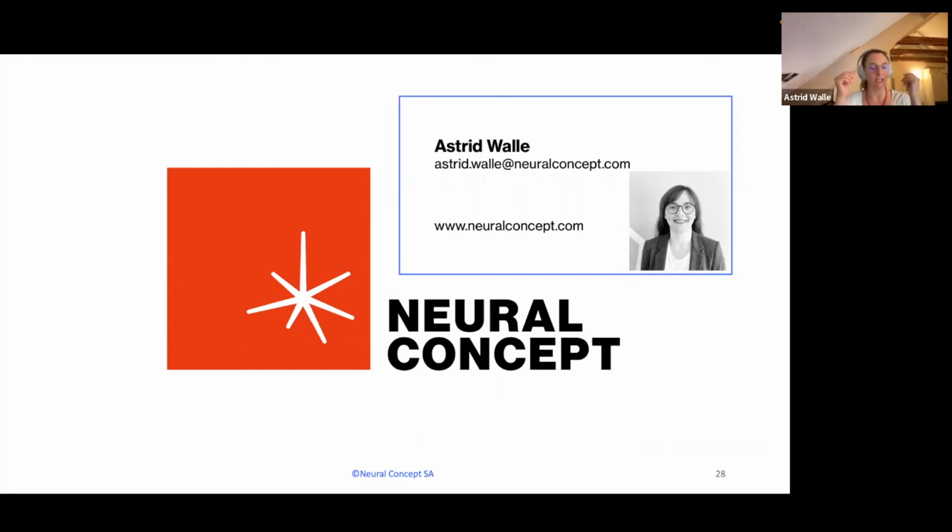Yes, of course. But I have not seen really weird shapes generated. In general, and this is true for every surrogate modeling and optimization project, in the end, when the optimizer says it found the optimal design, you will always take it and run the simulation again to make sure the results are actually true. Most of the time it will not be a perfect match, but hopefully you have gained something. The surrogate model is never 100% correct, so you always have to rerun your best design in the end and validate it yourself.